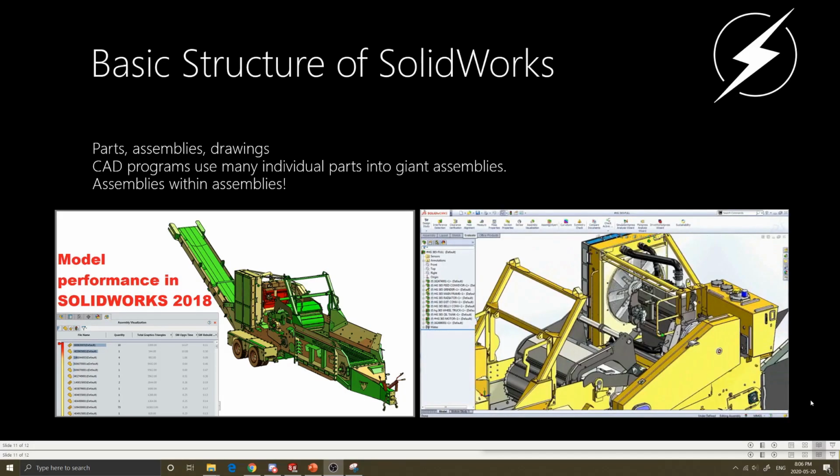There are three essential file types in SolidWorks: the part, assembly, and drawings. You are able to build various individual parts into something called a part file, and these parts can be simply made from sketches or fully modeled objects. You can later reference all these parts in a single file called an assembly, which allows the designer to arrange all these parts in a specified manner, allowing the parts to interact with one another. Drawings can reference both assemblies or parts. These drawings, or engineering drawings, are blueprints for your model and are important for manufacturers and the production of your final design. They include important measurements and tolerances that manufacturers will need to know.